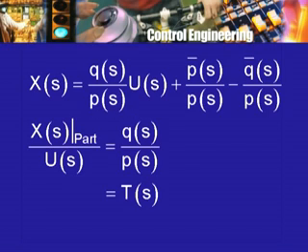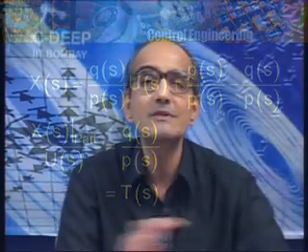So, for stability, understood in the sense that all these terms will go to 0 as t tends to infinity, and this is one concept of stability that I have been talking about, for that stability to hold, the roots of P(s) must all lie in the strict left half plane.